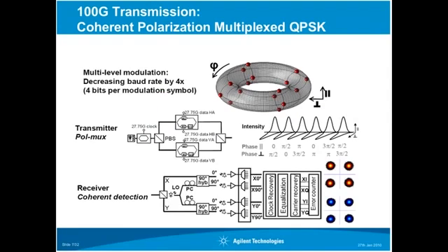So in terms of testing, we will probably see different kinds of test methods. The common DCA, which used to display an eye diagram, is not enough anymore. People are wanting to see the constellation diagrams, like here on the bottom right. But if you take the polarization as another parameter, then you need a third dimension. So some people draw these nice pictures like this. You duplicate the constellation diagram into some sort of toroid space, which allows you to visualize what's happening on the link.